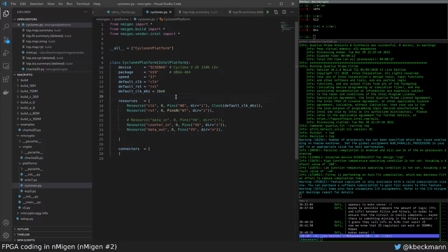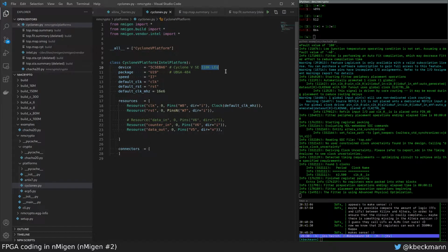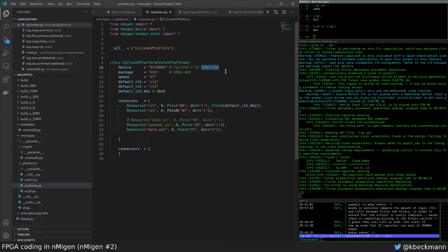Really hard to say because the Cyclone V is much bigger. I think it's like 100k LUT, yeah, 110k LEs, whatever that means, but it's a pretty beefy one. So yeah, it's a big one, but I don't know how fast it is. No idea. And from other benchmarks, it seems that it might be a little bit slower than the Xilinx Series 7 Artix.